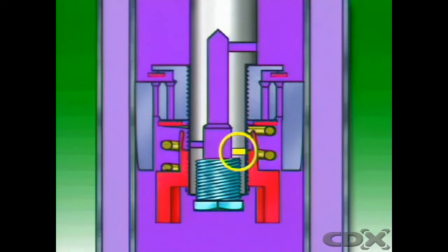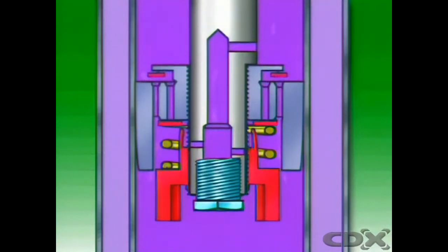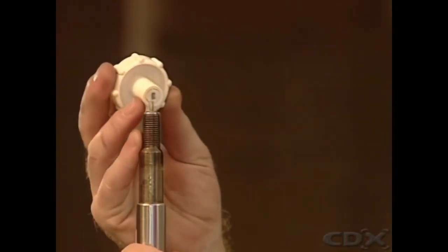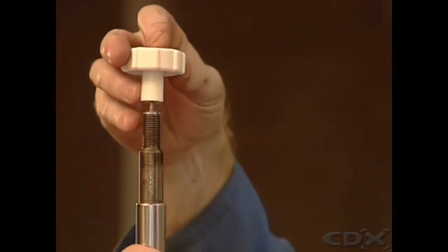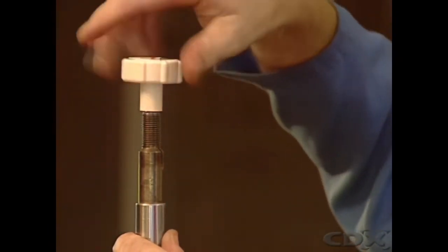Closing some of the orifices and increasing the spring force applied to the valves makes it harder for fluid to flow through the piston. This increases the dampening effect of the shock absorber. The method of changing the position of the valve varies. On this model, it is adjusted by a spindle that reaches down inside the plunger.